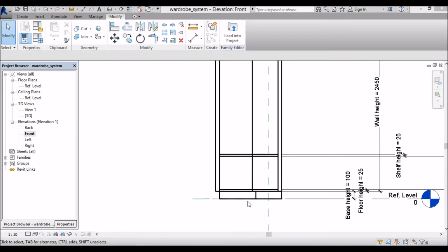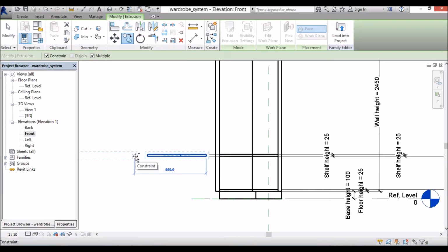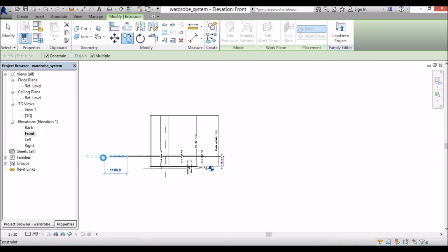Now what we want to do is to make 3 more copies of this shelf, and they'll all be spaced at that 455 millimeters apart. So click on the shelf to select it, and up here next to rotate is the copy tool. Now because I want 3 copies, I'm going to click in multiple, and then I'm going to click on a corner of the shelf and copy it out. 1, 2, 3.